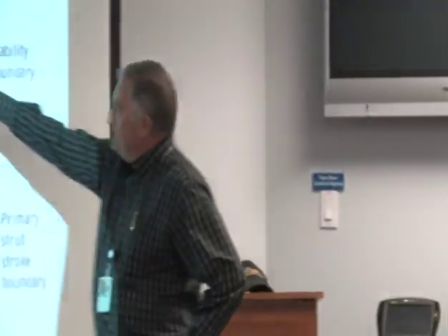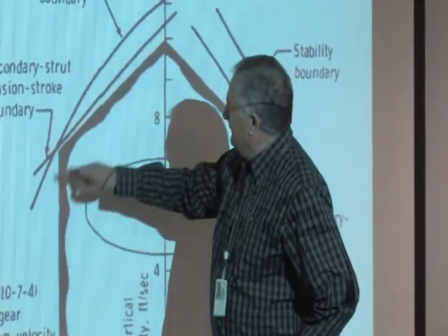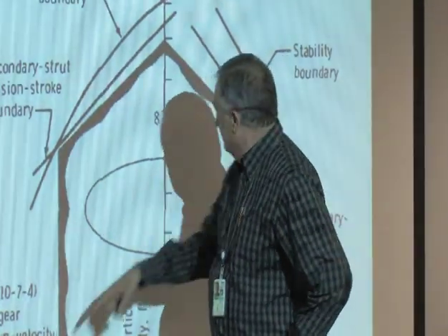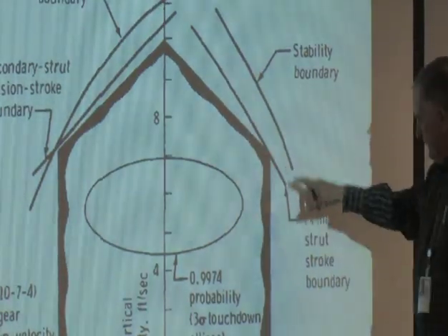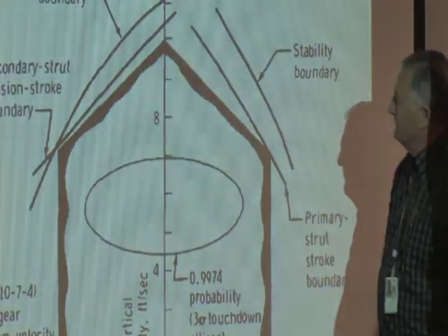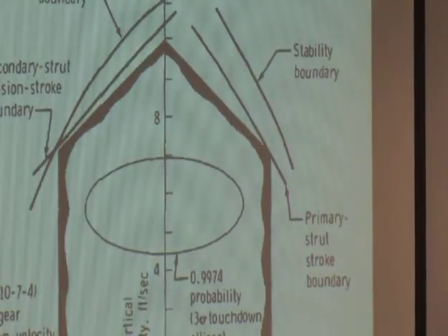Coming up with this, we started out with 10 feet per second here, and went over to 5. And you can see we were violating that envelope. So then we cut it down to what we call the doghouse, where it's plus or minus 4 feet per second, 10 feet per second sink speed. That point right there is the highest kinetic energy point.